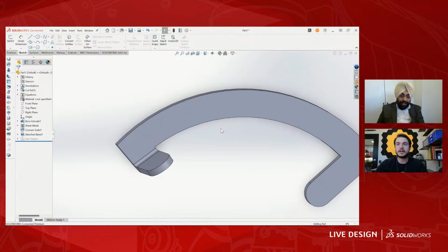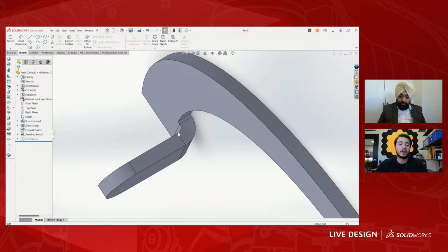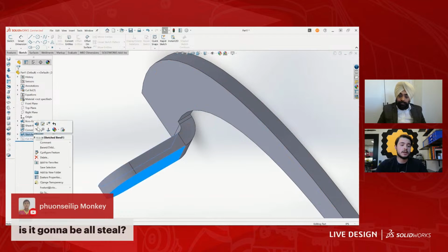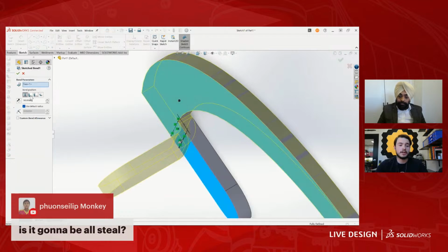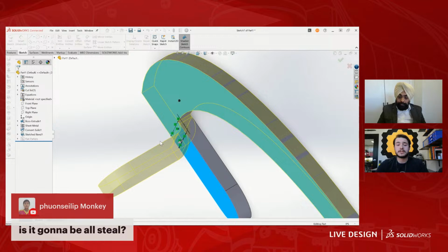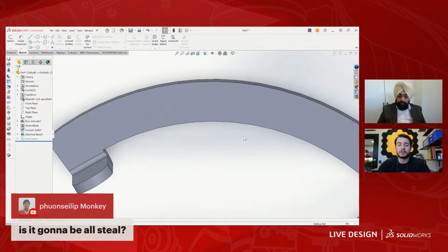Yeah. Exactly. And the nice thing with that is you can now go fine tune that without having to change your bend angle, or if you're using a different kind of brake or you're using a CNC press or something to do the bends, you can actually adjust the location of the bend directly in here. So you can have it be on the inside, the outside edge, down the center line. Really gives you a lot of flexibility while maintaining the same geometry.